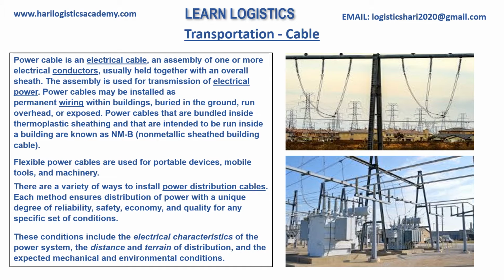Power cables may be installed as permanent wiring within buildings, buried in the ground, run overhead, or exposed. Power cables that are bundled inside thermoplastic sheathing and that are intended to be run inside a building are known as NM-B, non-metallic sheathed building cable.